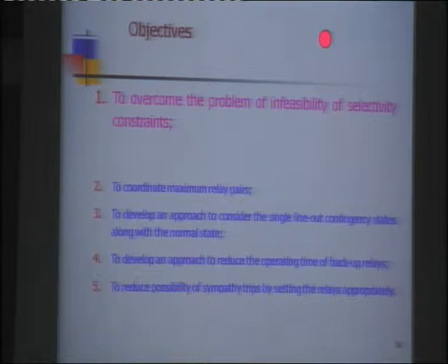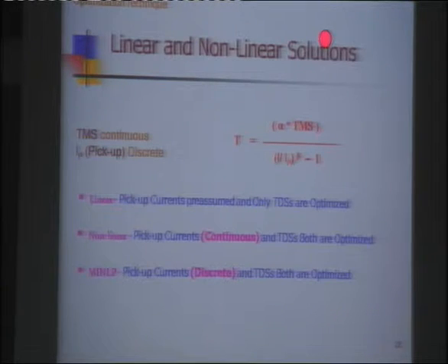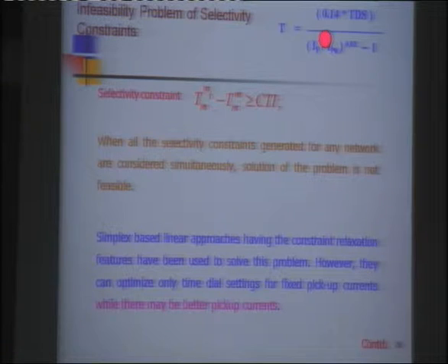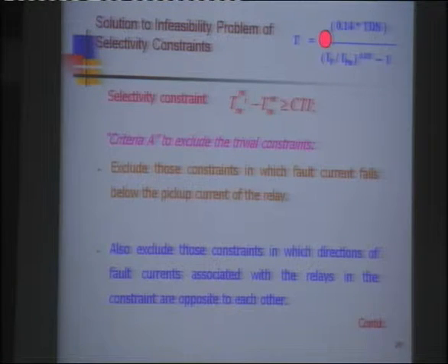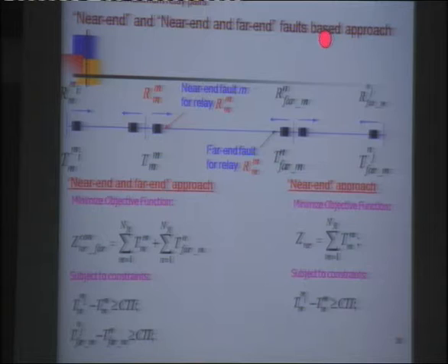For a system of 6 bus, there will be 132 constraints. For a system of 14 bus 20 lines, there will be 424 constraints. So you can realize that as the system size grows, there will be more and more constraints, and it becomes a huge non-linear optimization problem, whose solution will be found in a non-linear environment, and it is a combinatorial problem, making cumbersome constraints in opposition to each other.